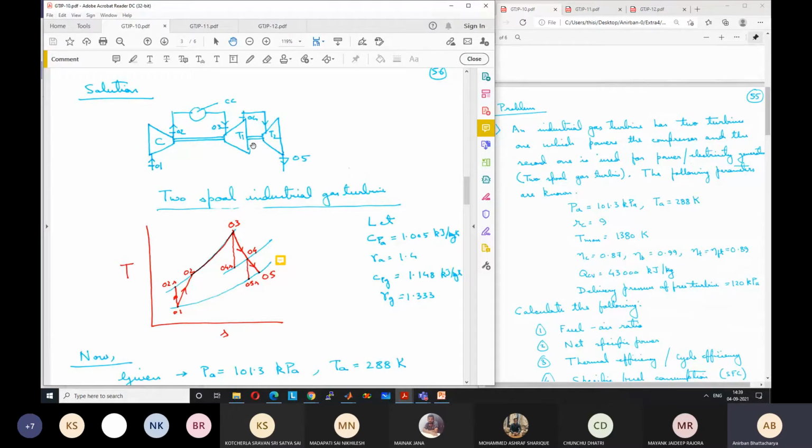One shaft runs the compressor and the high pressure turbine assembly, and the second shaft runs the second turbine. It passes through the outer shaft basically. They are like concentric cylinders. Between the compressor and the turbine there is obviously the combustion chamber, then the high pressure turbine, and then the low pressure turbine. The entire work of the low pressure turbine is used for running the generators, basically for generating power. The entire work output of the high pressure turbine is used just for running the compressor.